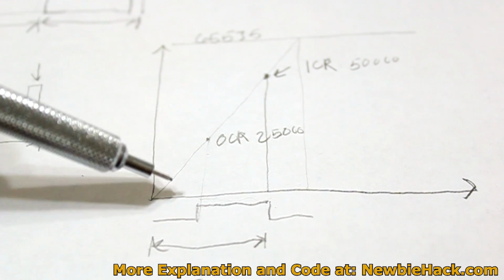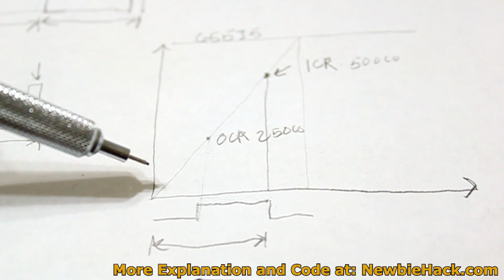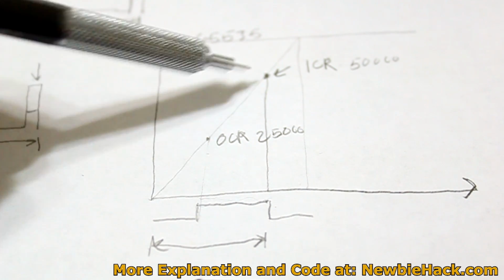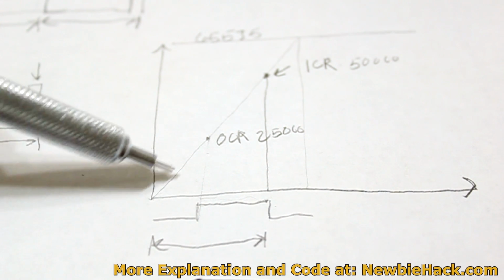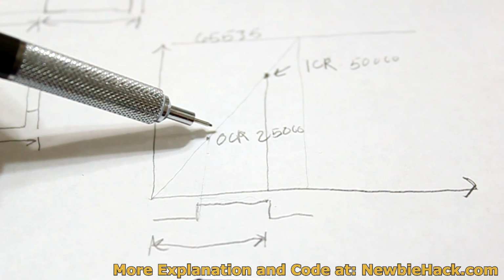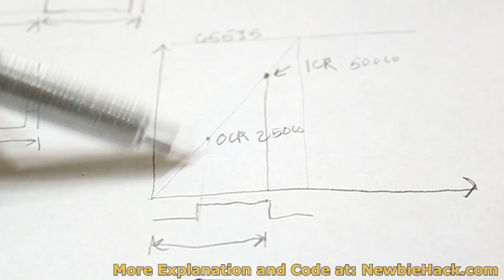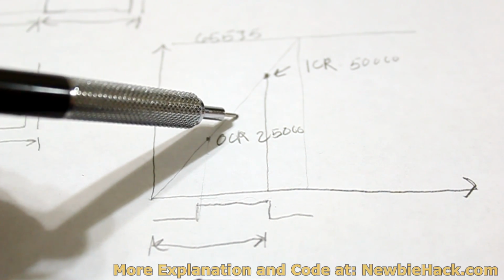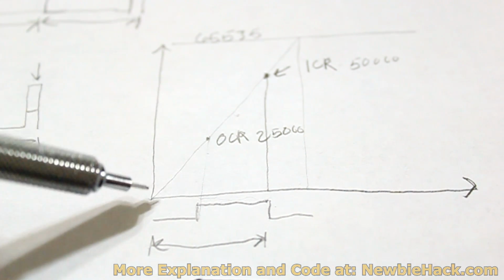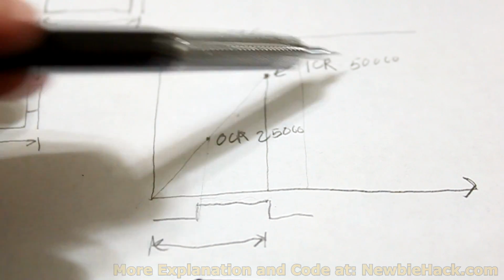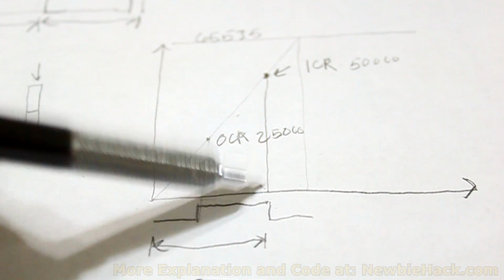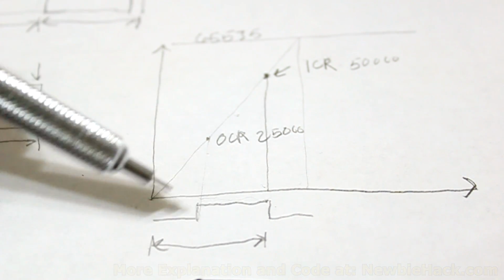So in this video you've learned about PWM, pulse width modulation, and what it takes to create the pulse width modulation using the timer. In our next video we're going to actually program for the servo to be controlled using the 16-bit timer and the PWM. And we'll do it with the fast PWM, which is assigning a top value to ICR, and then it goes back down to 0. We can also do it with phase correct.